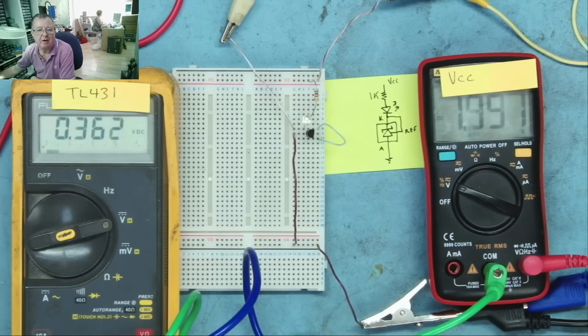If we increase the supply voltage then, as we did before, you'll see that the LED starts to come on at a little bit of a lower voltage, so the TL431 does start to conduct. And then at 2.499, you can see there, the TL431 is now holding a stable voltage. In fact, it's 2.5 exactly. And I can increase or decrease the supply voltage. So we have a slightly different but very similar behavior. Okay, you can see it there.